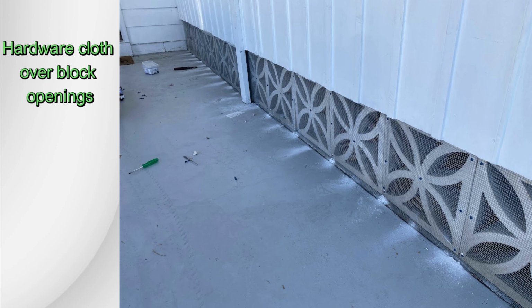As you can see here, we used an interesting pattern. We did 3 concrete screws down each side of the block and 1 in the center, and we found this anchored the hardware cloth really well to the block. You have to make sure when you're doing this you don't drill too closely to the edges or you can crack the block. But I can tell you we had probably 70 or 80 blocks on this home. We didn't crack any blocks. We were able to use a concrete bit, put the concrete screws in, and this exclusion came out very nicely.